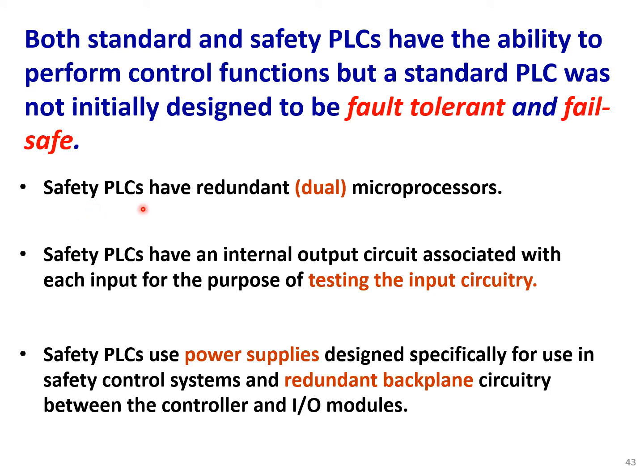Safety PLCs have redundant microprocessors or dual processors, so the extra one is used for backup. Safety PLCs have an internal output circuit associated with each input for the purpose of testing the input circuitry.